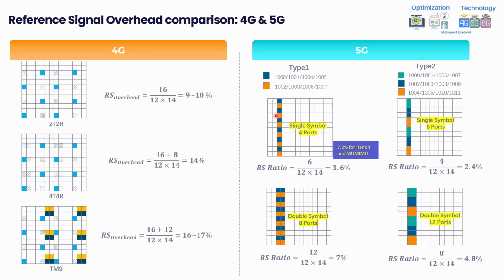Now comparing to the PDSCH DMRS. First of all, the PDSCH DMRS has two types, type 1 and type 2. Type 1 has more resources compared to type 2, as you can see here. For example, if you are speaking about only a single symbol, it can consume a minimum of 50% of the resource elements within the symbol. 50%, meaning every second resource element can be used for the reference signal.